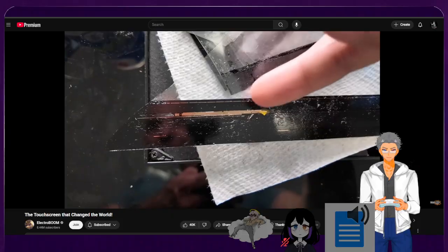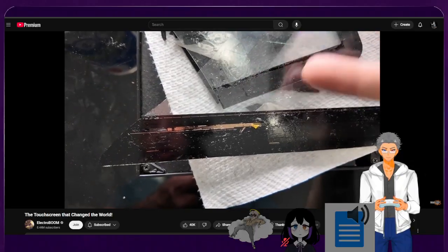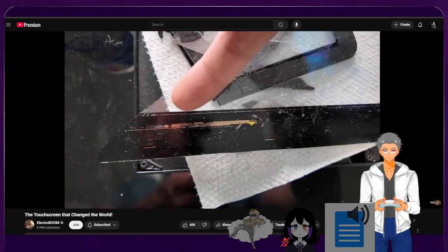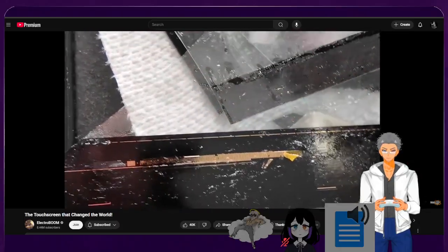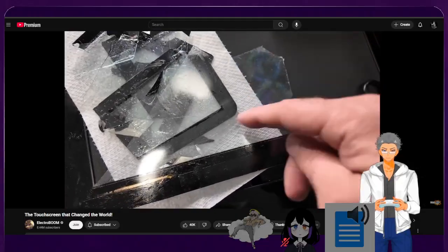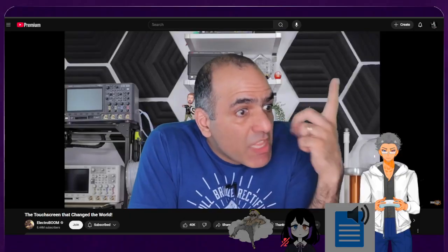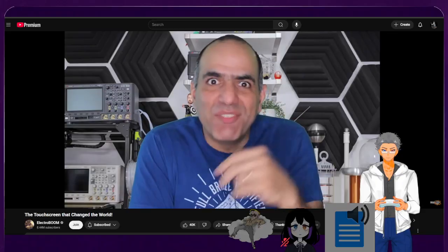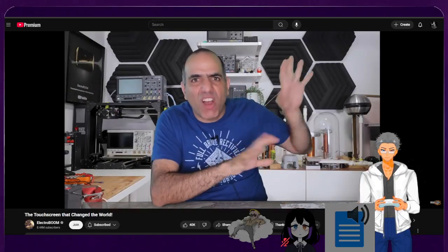Well, at least here you can see the tiny contacts that connect to the rows and columns of the touchscreen panel. And up here, you see, for example, the columns of the touchscreen every half a centimeter apart. But the actual rows and columns are so transparent, you can see nothing. Let me make a 2D capacitive touchscreen for you. A touch sensor. You're on your own for the Bob is your uncle part.